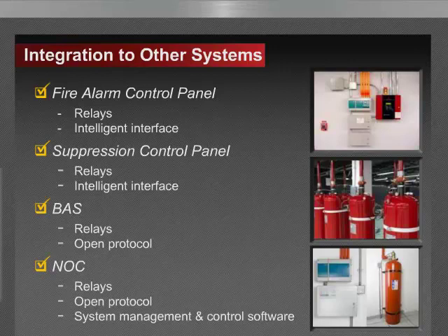The more air handling units that you're monitoring, the more dilution that you're introducing, and the larger the fire growth may be by the time it detects, depending on how much dilution is actually being introduced into the system. So good practice is generally one pipe per air handling unit for the average size air handling unit.